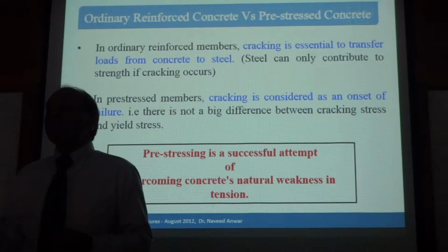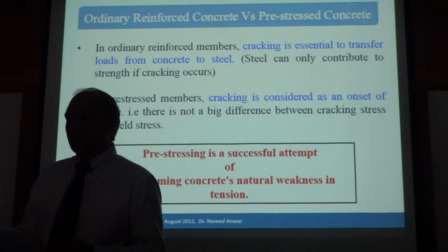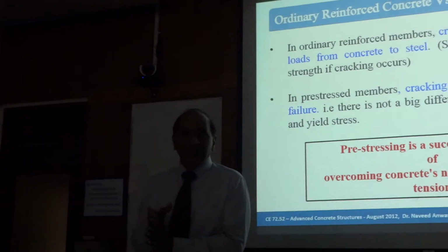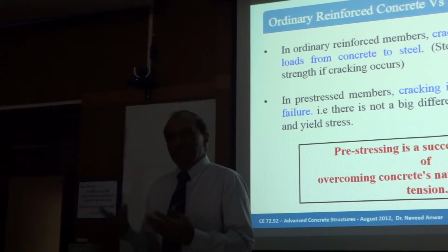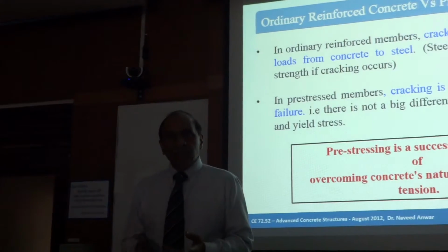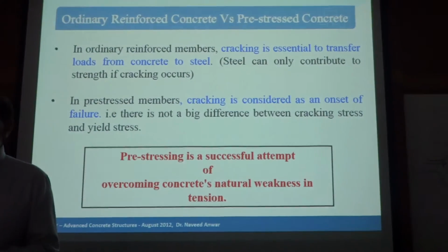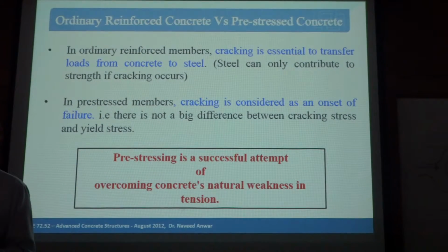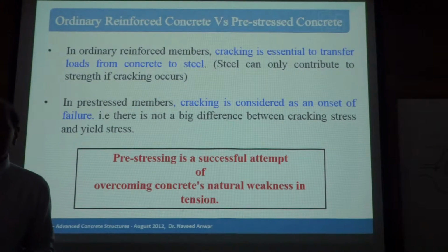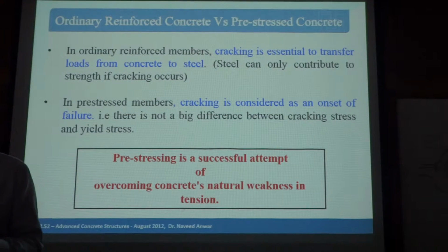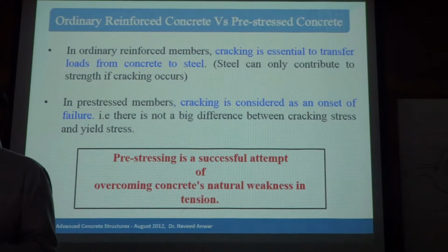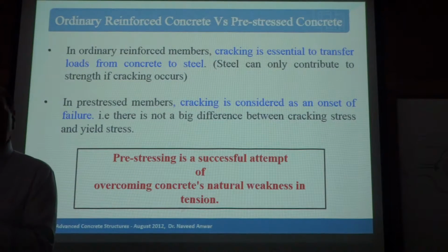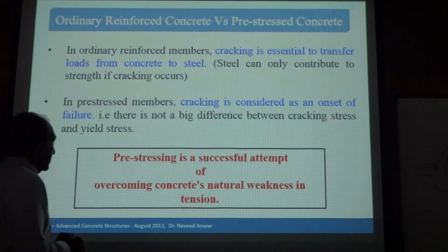It becomes just like any material, steel or plastic, because the two behaviors, tension and compression, which are different for reinforced concrete, are no longer the case. Now compression and tension can be treated in the same way. So it makes your analysis and your handling of the material much easier, because now you can deal with it as an isotropic, homogeneous material, rather than a material made up of aggregate, cement, and reinforcement. It kind of disappears, right? So we have these two advantages of prestressing.